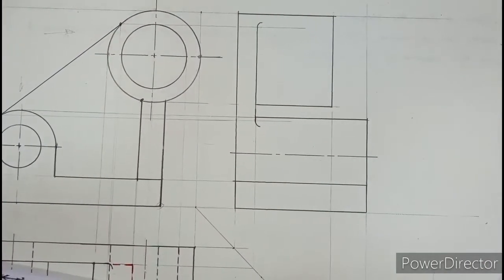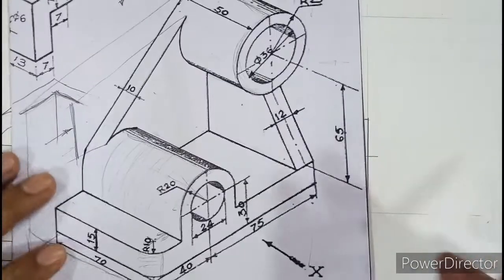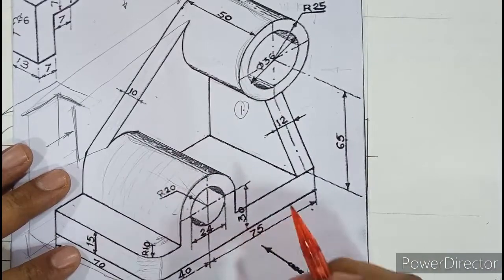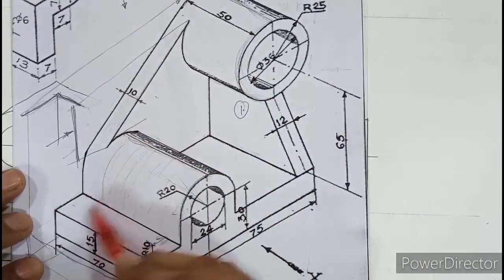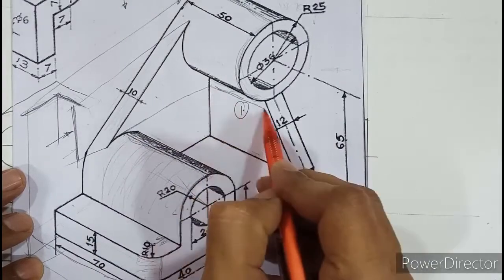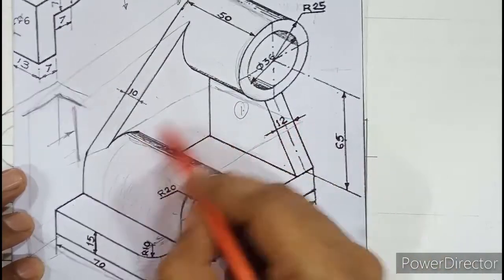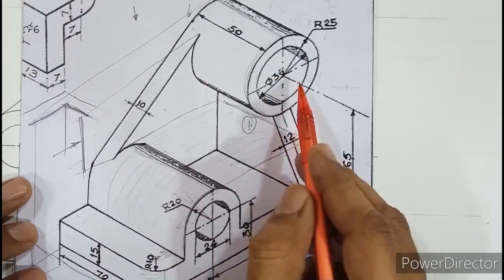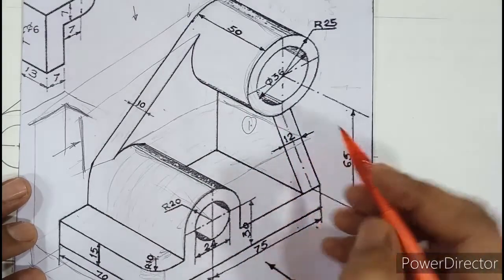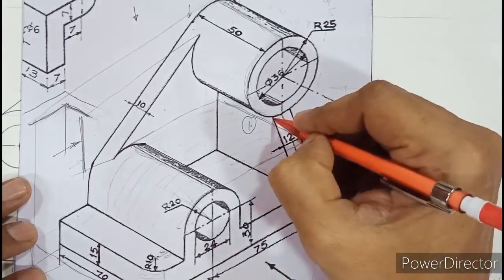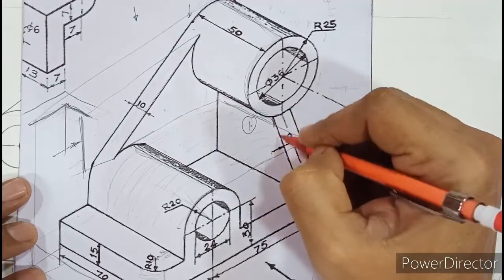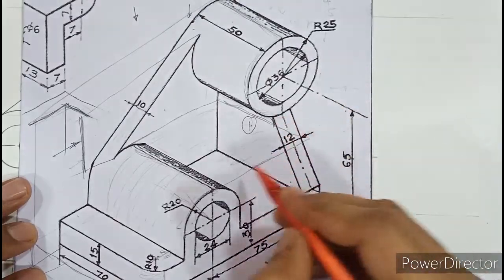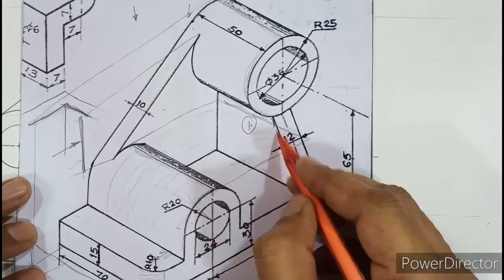Okay, so I hope this is clear. Now some very important lines I am going to discuss. What about this rib number 1 in the side view? So the answer is, when you look from the side, and if you project something here, try to visualize, you can see everything above this plane, correct? You cannot see what is below this plane. So if you look at the edge of this rib, you can see some portion of the inclined edge and the remaining cannot be seen, because some portion of the edge is above this plane and the remaining is below.